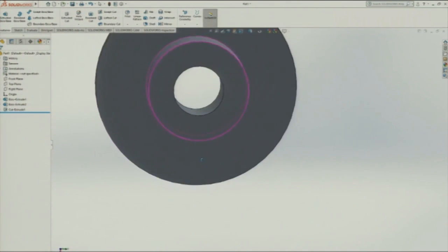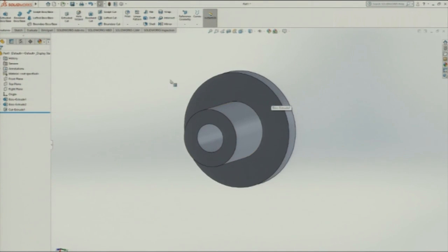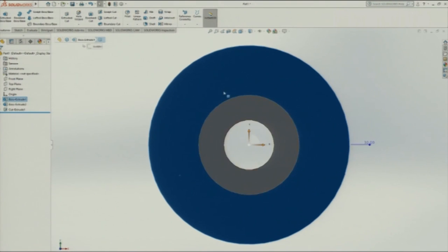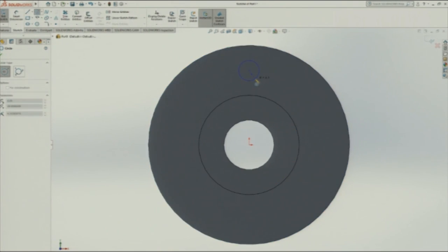This is the shaft diameter that is made now here. Now we need to drill a hole here for the nut and bolt system. The nut and bolts should be perpendicular to the axis here. The diameter for the hole is 8 mm. So, for 8 mm diameter, I put 4 mm as radius.